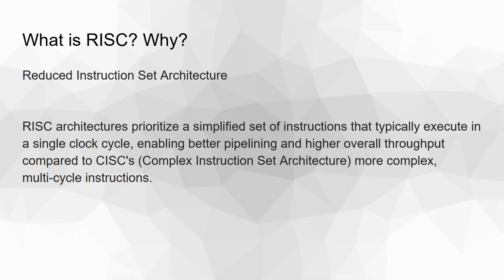This has the added benefit that if this is on an embedded system like your phone or a laptop or even a drone, reduced instruction set architecture uses less power because these are much more simple instructions. Now, this does mean that RISC might be a little bit slower at more complex tasks like 3D rendering that require large amounts of multiplications.